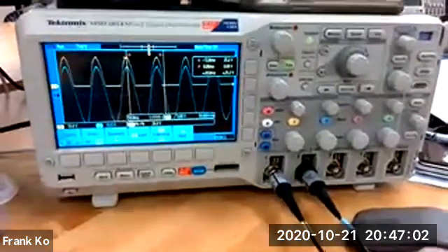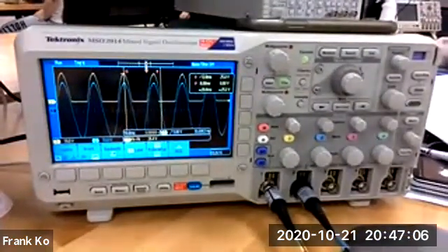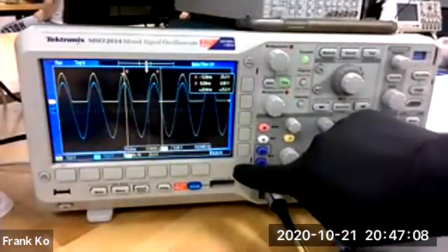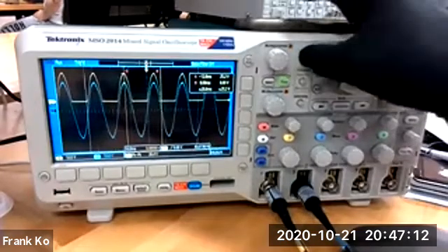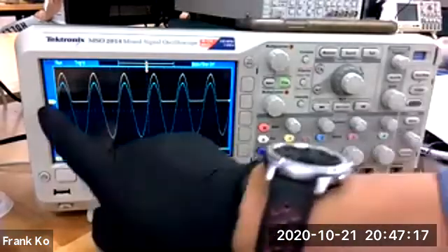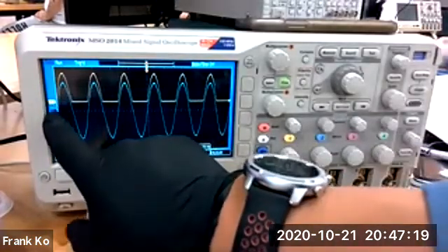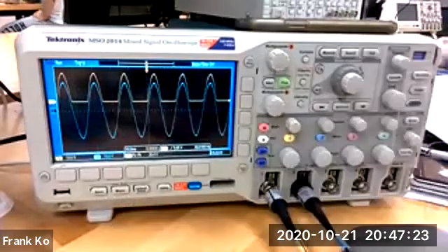All right. Focus on that focal plane. Take off all the menu stuff as much as possible. Take off my cursors as they're not needed. And what to do is to line up your yellow and your blue flag so that they are lined up on the 0 volts line.